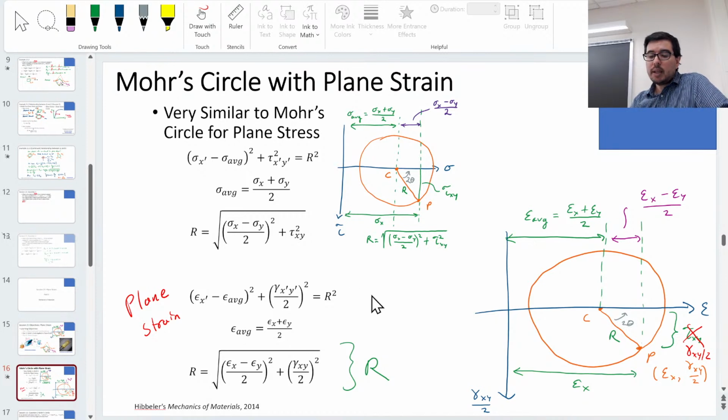So this is now the second thing that can be confusing, because we have a 2 theta already in our Mohr circle. So 90 degrees on Mohr circle corresponds to the element rotating 45 degrees. And now what we're saying is that gamma xy over 2 is what we have in the vertical direction.